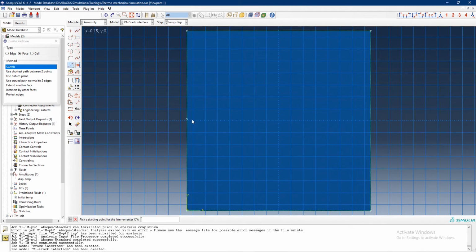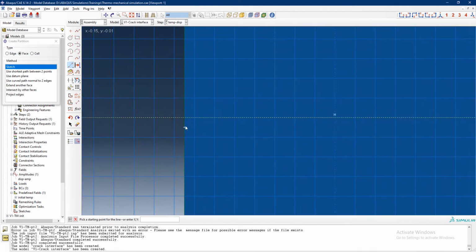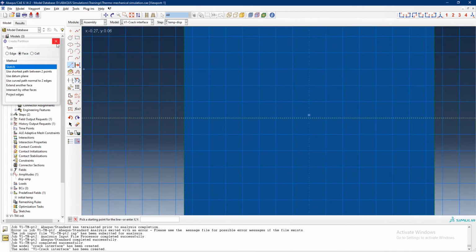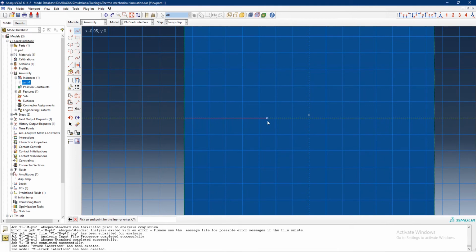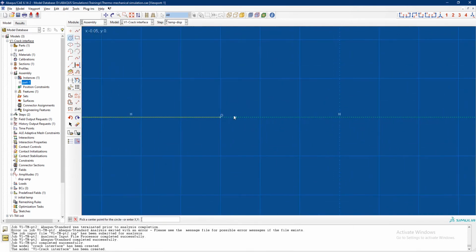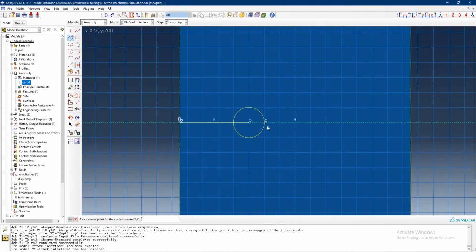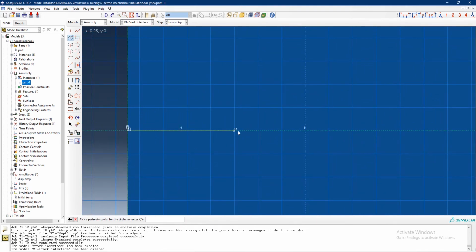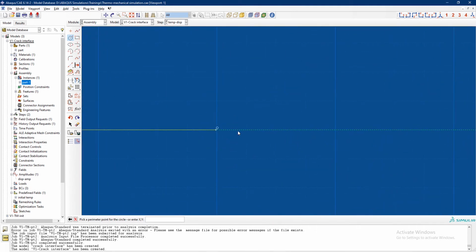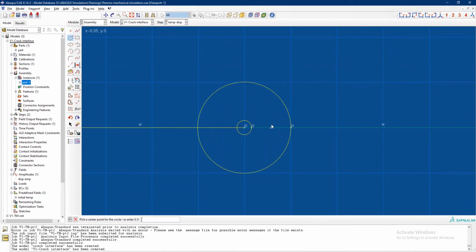Defining a contour integral crack is tricky here, so I will just follow the SOPs which I know work. So this is a crack, and to define a spider mesh on its tip, what we do is, oh, this is quite big. What we do is we define a small circle, and then we define a big circle around it.